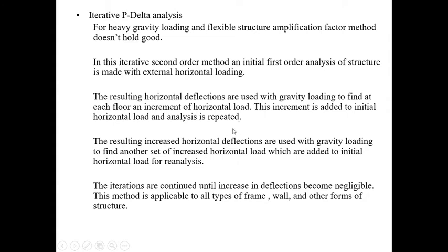So here it is an iterative method, that is, we go on adding the increments of horizontal load. The resulting increased horizontal deflections are used with the gravity loading to find another set of increased horizontal loads, and again whatever increment there is is added to the initial horizontal load for reanalysis.